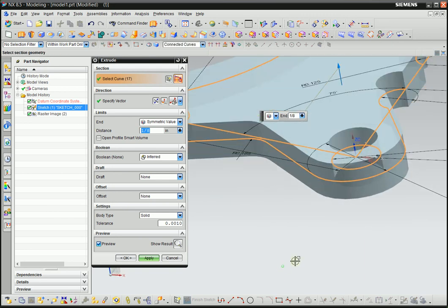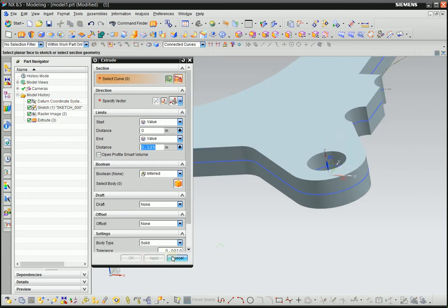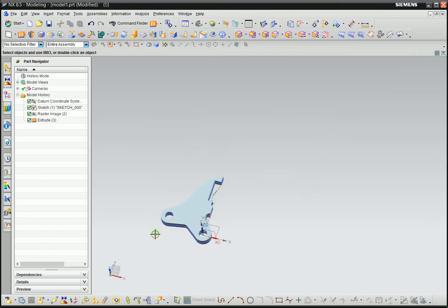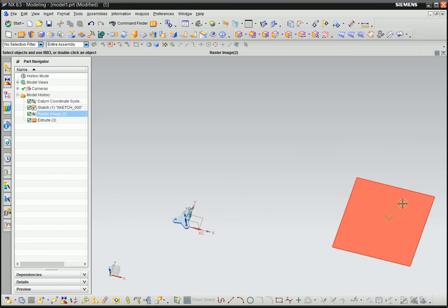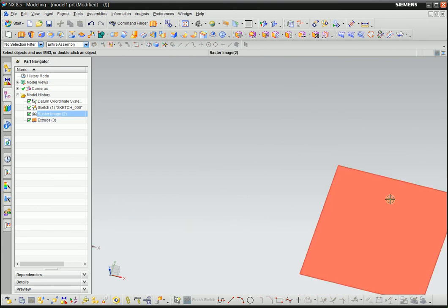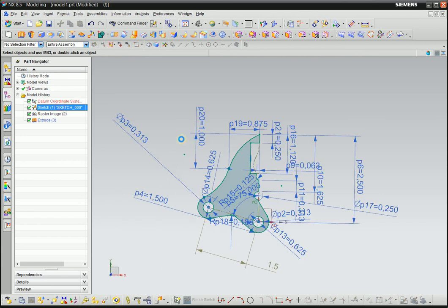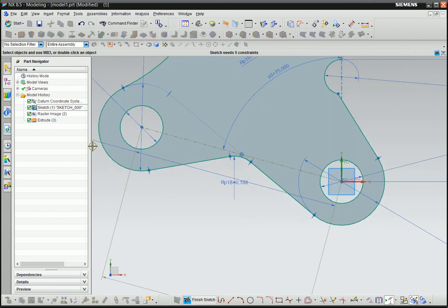Yeah, so you extrude symmetrically. That way, when you extrude this thinner part, you just need to change the distance here. It's gonna make sure the thinner part is in the middle of this thicker part. Okay, apply, cancel. Now we have one piece here. We can keep doing the teeth, or well, maybe the little ear is easier to do that. Okay.